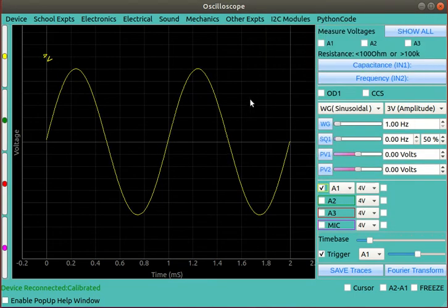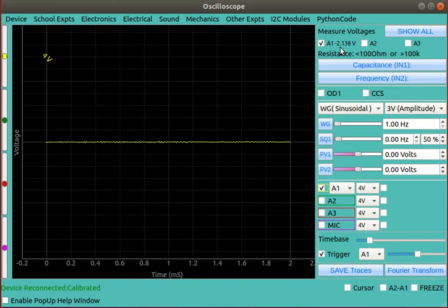Okay, so on this side you will find some tick marks, A1. If I tick that, you can see this just jumping around. Actually what is happening is it is measuring the instantaneous voltage on A1. So to see anything meaningful, I have to connect it to a DC source.